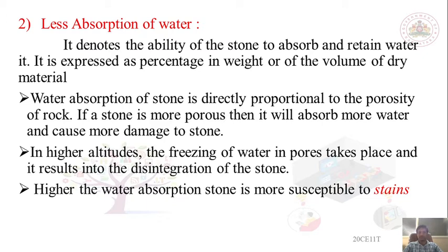It freezes at a temperature of around 0 degrees centigrade. In those cases, what will happen? The pores present in the body of the stone will absorb a certain quantity of water, and they will fill up with water. Then at the freezing point, that water will become frozen.